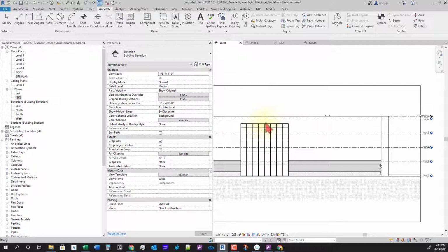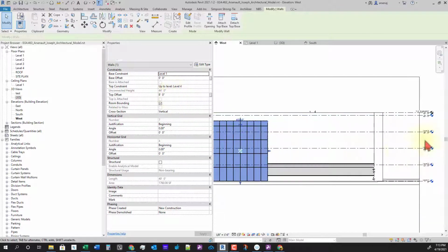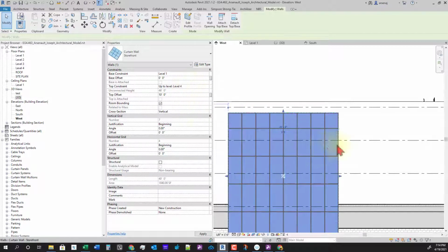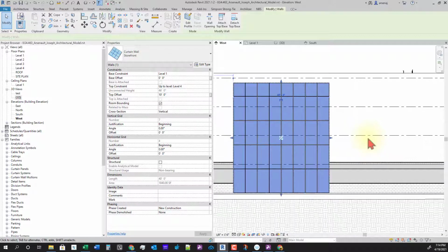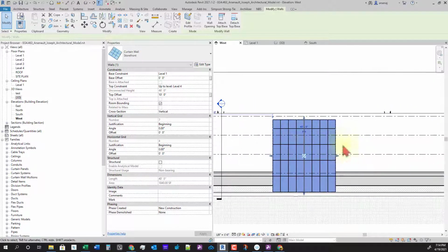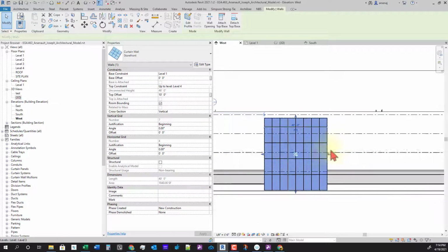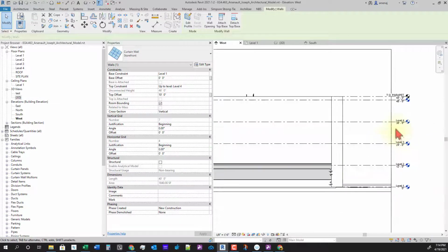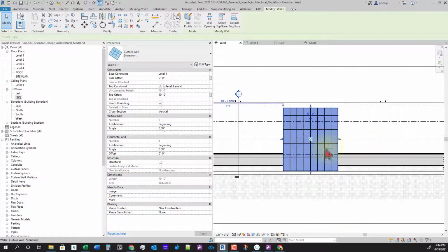Oops, I'm going to save. That means that the top of our window would be right at the ceiling height of 8 feet. I'm going to actually do 10 feet above because we gave 12-foot floors. So I'm thinking we might want a nice tall ceiling on that level 4 and all the levels. And so we're going to make that a pretty tall wall here.